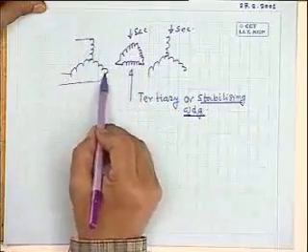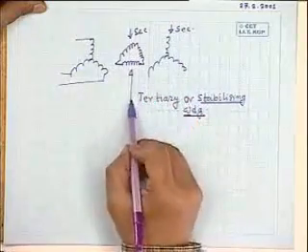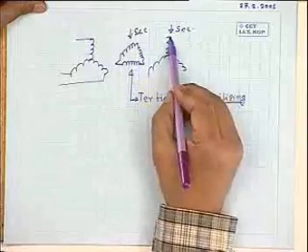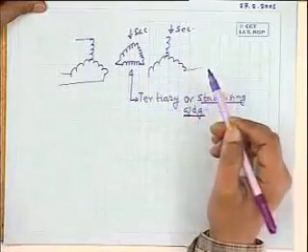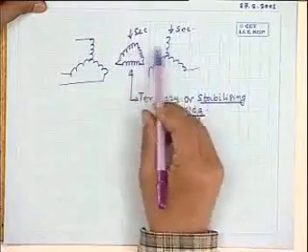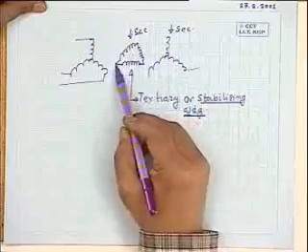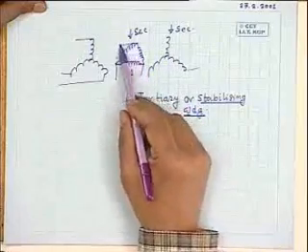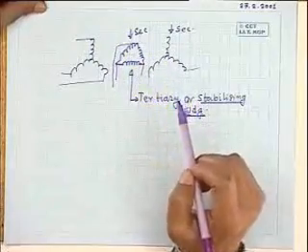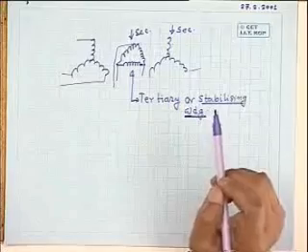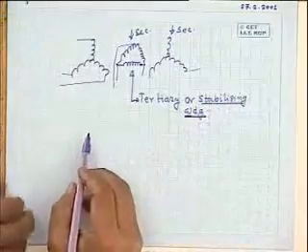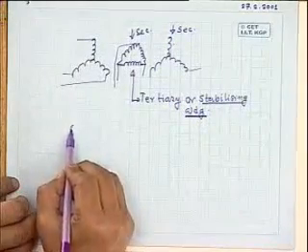But you remember that a transformer having both secondary winding and tertiary winding, which is called like this, you can supply load from both the secondaries. Sometimes, if it is needed, that you can have different two voltage levels on the secondary side, different number of turns. You can also supply tertiary winding, can be used to supply also additional load if needed, like that. Now, another problem with star-star transformer that I must tell is the oscillating neutral.